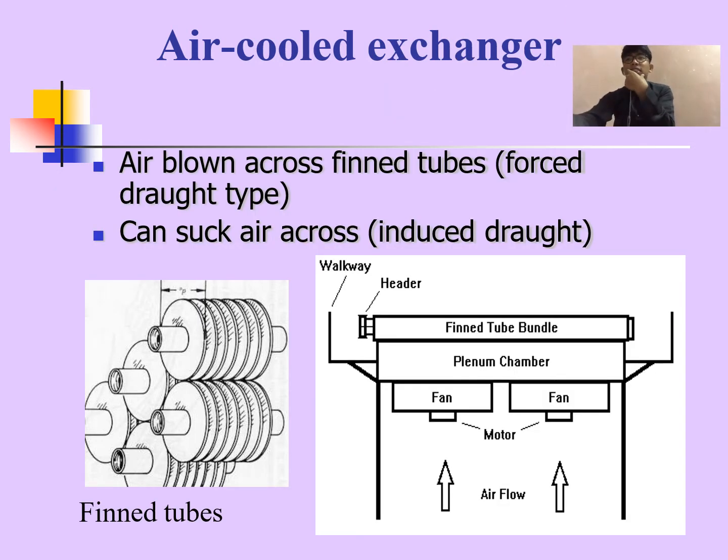An air cooled exchanger is air blown across finned tubes, forced draft type, and can also suck air across in induced draft. For more information, air cooled heat exchangers are used to transfer heat from process fluid to ambient air. Process fluid is contained in a heat conduction tube, and then atmospheric air, which serves as a refrigerant, flows vertically across the tube to dissipate heat.